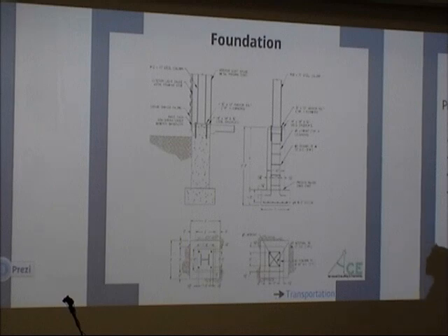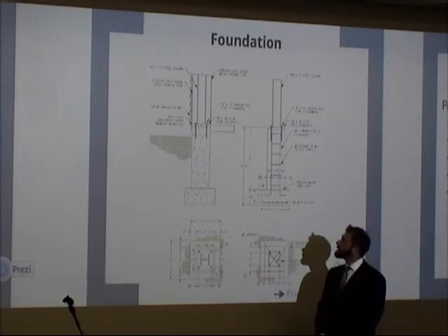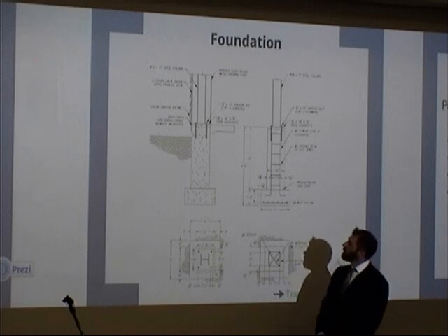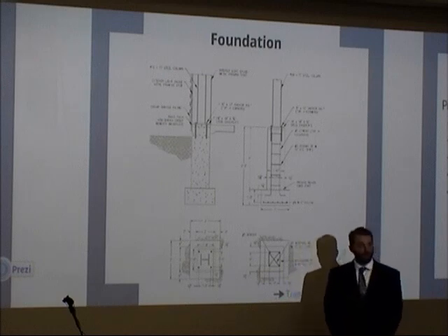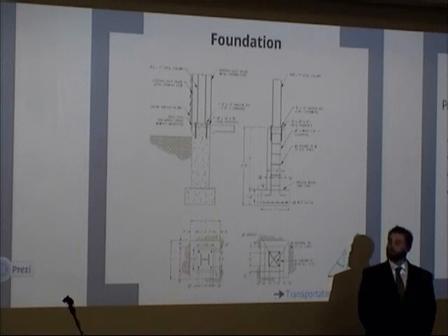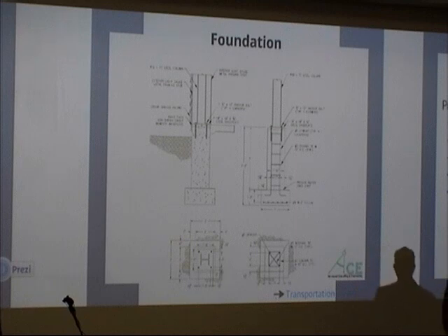I'd like to bring you to the top now, to the top of the actual concrete column where it meets the base plate. We have a detail here in which the base plate connects to the concrete column through 4 3/4 inch anchor bolts. They have leveling screws at the bottom on which the base plate sits. You level those during construction, then add your top nuts and tighten those down to your required torque. Then you hand pack grout underneath the base plate, between it and your already poured column, to ensure that the anchor rods are not supporting all of your downward force, and that you actually are getting bearing in the concrete.